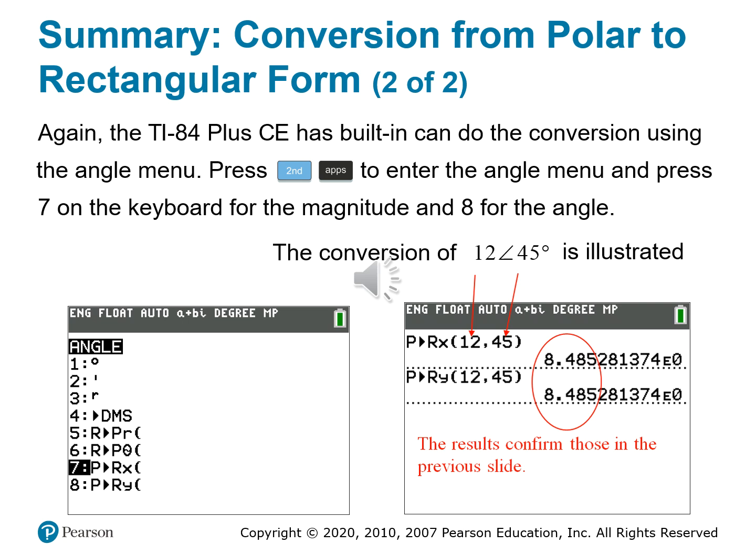Now, again, because it's an angle 45, I know that the legs of the triangle are going to be the same magnitude. So A and B being equal, I'm expecting that. And this just confirms exactly what we calculated by hand on that previous slide, where we had 8.49 plus j8.49. So what's the point of all this?